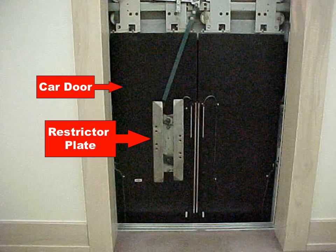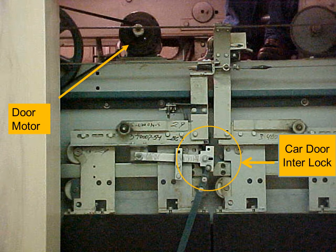This slide shows the actual elevator car in the landing zone at the elevator lobby. The hoistway door has been opened and is out of the way. The restrictor plate shown is there to prevent occupants of the car from opening the car door more than a few inches. When the elevator car enters the landing zone, the hoistway door catches the restrictor plate and allows the door to open. The top of the elevator car houses a motor that opens and closes the elevator car door. When the car is in the landing zone, the elevator car grabs the hoistway door and pulls the hoistway door open as the elevator car door opens.